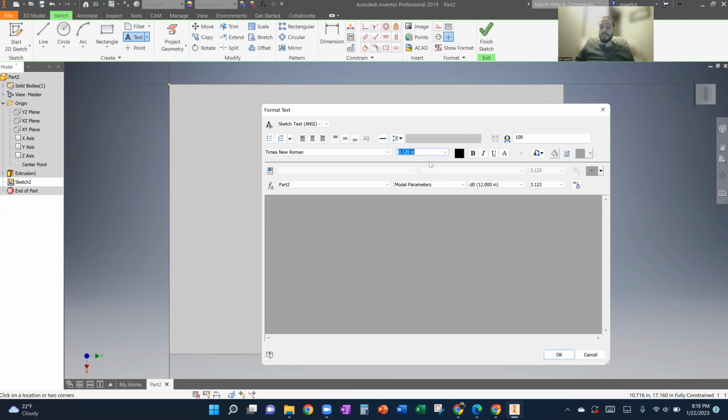But here I select my word height. Okay, that's very important, my letter height. So here I'm going to do like a 3-inch letter height because my board's 12 inches wide. That's really big. If you have something less wide than 12 inches, you're probably going to want to have that change. But there's some tricky parts to this.